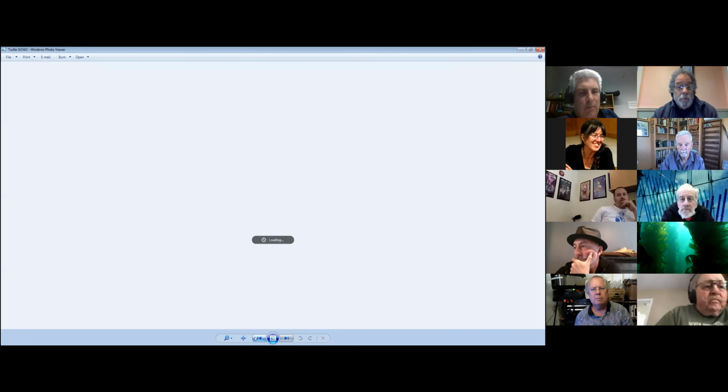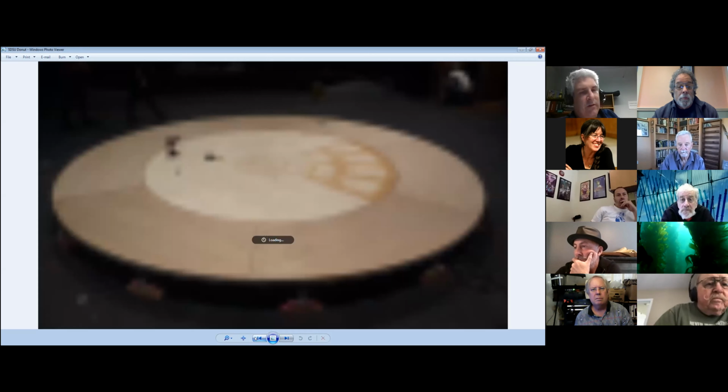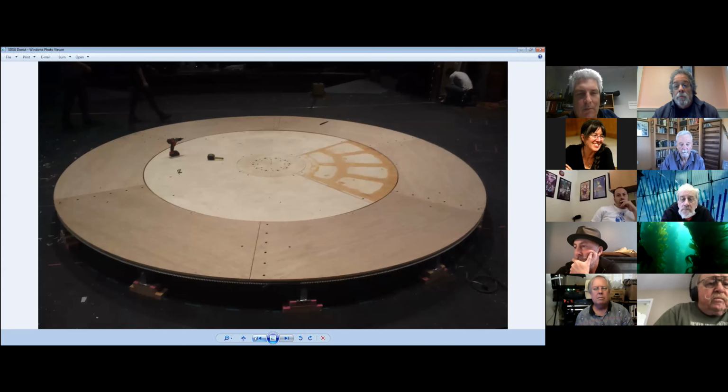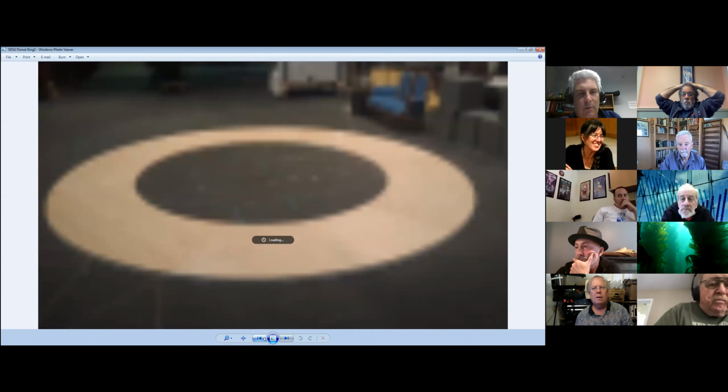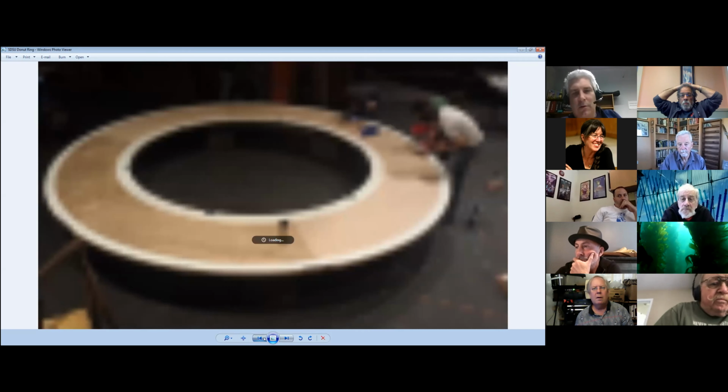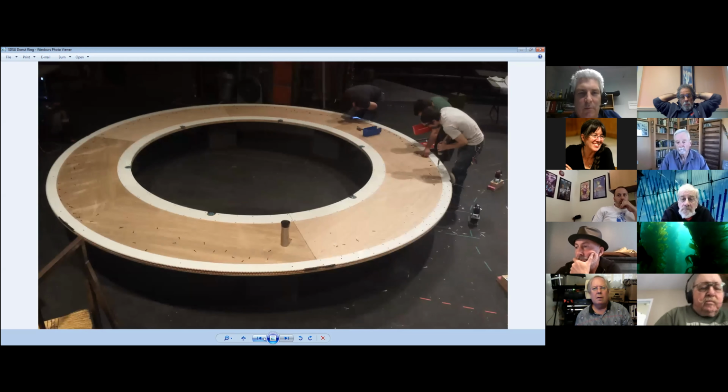So we end up with the cast of 14 all stomping going in one direction. We wanted a couple horsepower in there based on what we've done. In order to get that package to fit in the thickness they would allow for the tour deck, we went with multiple 1 horsepower friction machines, because we could never fit a higher horsepower machine under there.